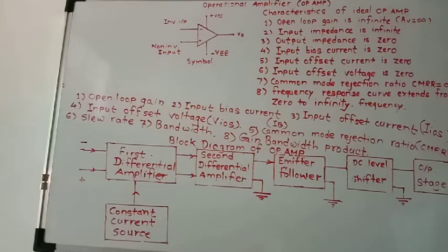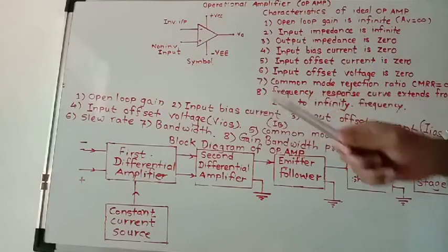A dual power supply is used for op-amp. Normally IC741 is widely used as an operational amplifier. When input is 0, the output can be adjusted to 0 by adjusting a potentiometer between the offset terminals 1 and 5.